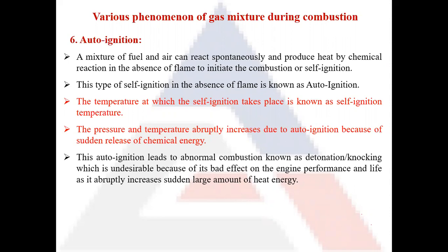The temperature inside the combustion chamber increases, and before the spark is ignited, the temperature reaches a certain limit such that, in the absence of flame, the fuel starts to ignite. This type of self-ignition in the absence of flame is known as auto-ignition.